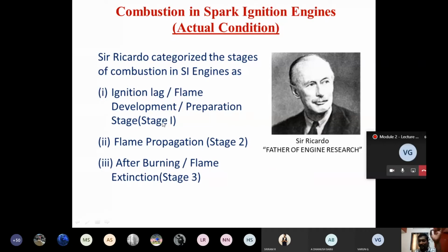And remember, all these 3 stages we are going to represent as soon as we introduce the spark inside the engine cylinder, right? After the compression stroke, spark is introduced. From there we are going to consider. So these three stages we are going to represent again in the P theta diagram, right? Here we are not going to consider the beginning of compression, only from the end of compression. In the actual case, we consider from as soon as we introduce the spark.